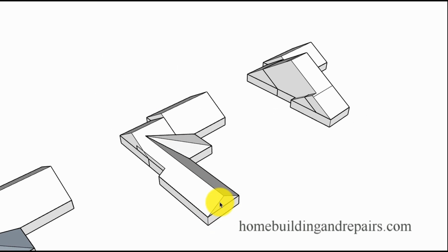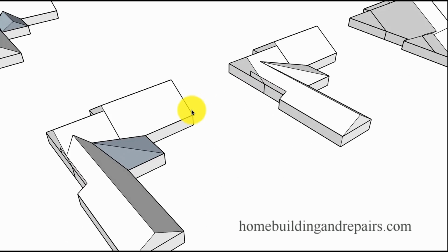Another view of it here. This gable would come back. So this would be the existing. This would stay the same. And you could just have a long hip coming up here with two valleys on the ends. And then a larger stucco wall here. This might come up about 10 feet if it's an 8-foot tall wall already.